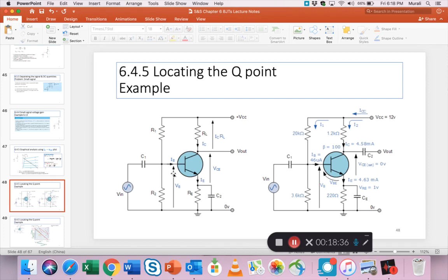But nevertheless, you can take a look at this circuit, and see all of the various parameters, IC, IB, IE, and then these biasing currents. This biasing network, using a voltage divider method with 2 resistors, is a very specific biasing method that you will study later on.